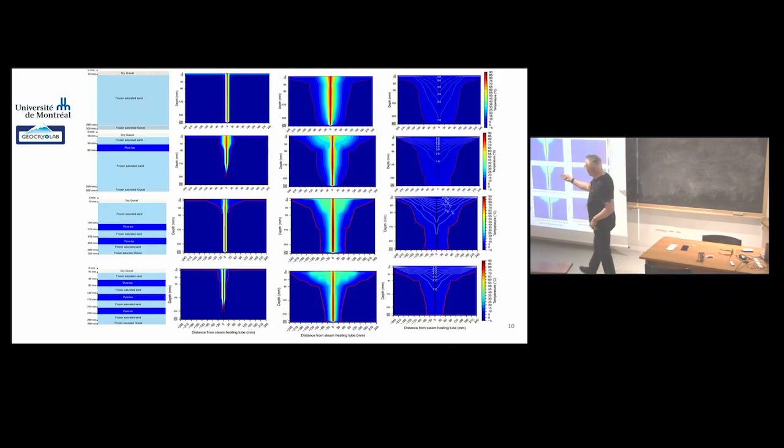So for instance, here you have 4 scenarios. Saturated sand, ice at the surface. The blue is ice lenses, for instance, and they're thick. Ice at the bottom, at depth if you want, and very ice-rich permafrost. So this is the thawing progressing, and then we know how it will progress, the amount of energy we need to put in, and where it will thaw. So where we need to remove the water, because it makes a big mess of mud. And so that's the application for that.